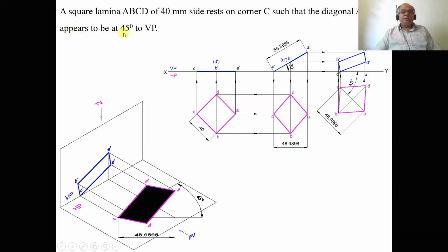From the projections of lines, from the apparent inclination you get the apparent length. Therefore, you reproduce the second position top view here without finding the beta inclination, because he has already given the apparent inclination, and since the length is also apparent, you transfer directly onto that apparent inclination line.